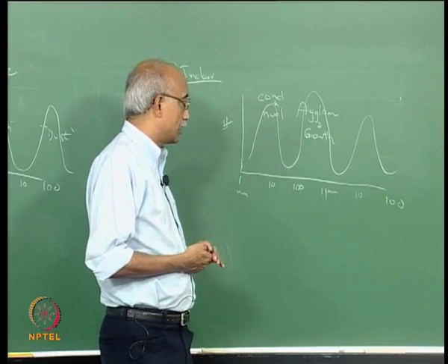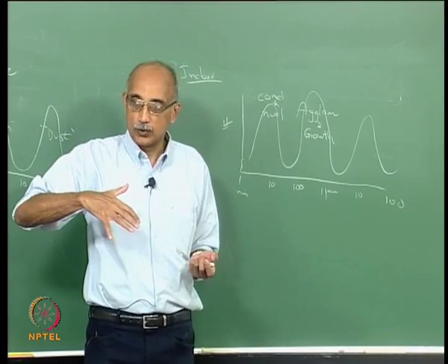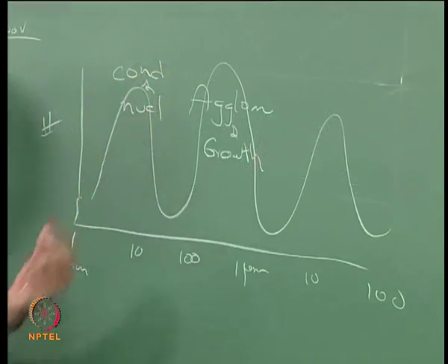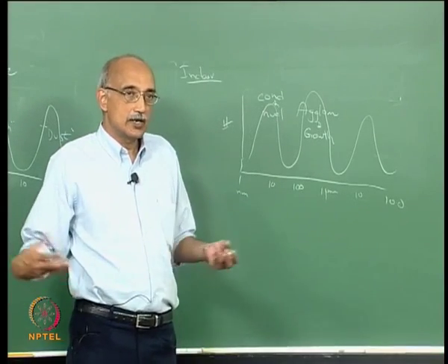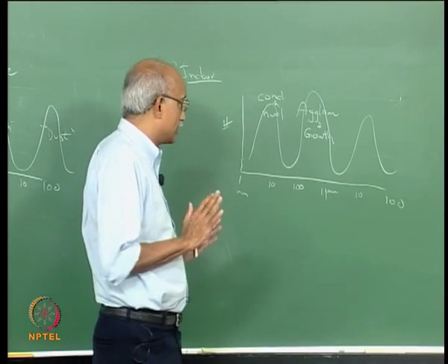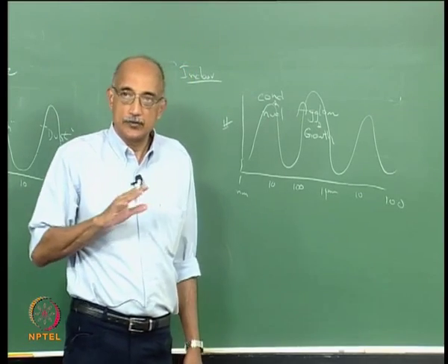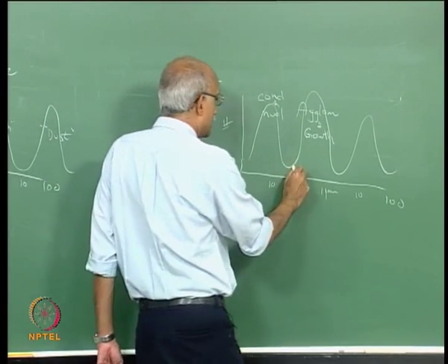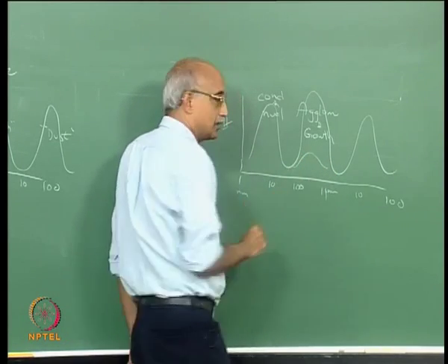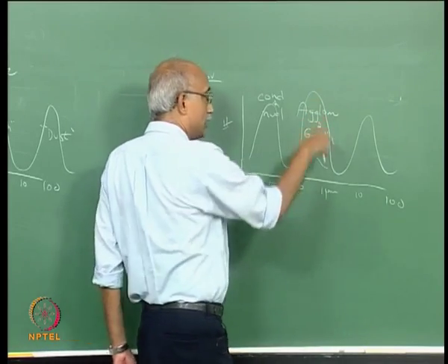Also, in a clean room environment which has very directed airflow, these fine droplets that are being produced will be quickly directed to go in a certain way and removed from the room. So they will never have an opportunity to find each other and start growing. So in a controlled environment, the phase of going from here to here may only happen to a very limited extent. So in a highly clean environment, you may get a peak like this, which is very, very low, compared to a room like this where this peak may be quite high.